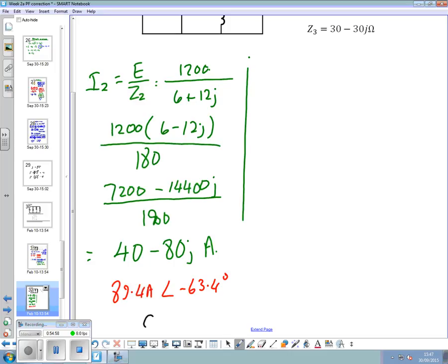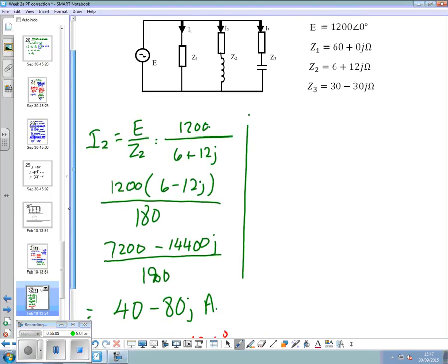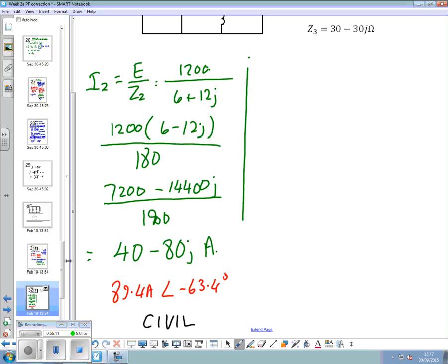It's always worthwhile to check: does that fit? We've got an inductor, no capacitance. In an inductive circuit, current lags the voltage. It's a good sign we've got the calculation right, and haven't got in a muddle with the signs of any numbers.